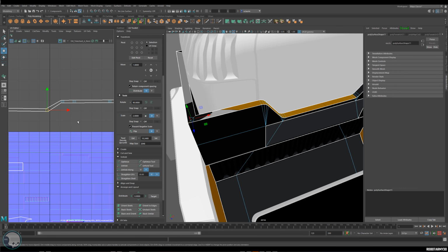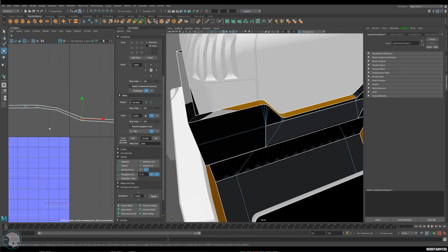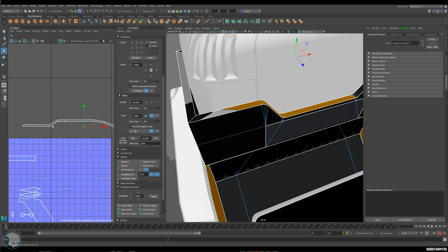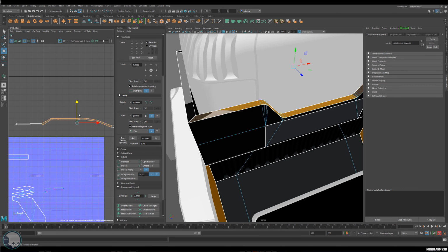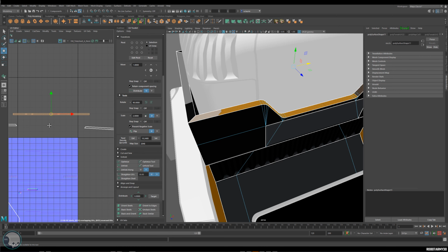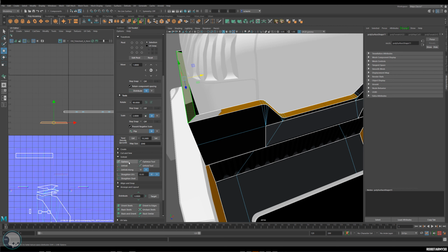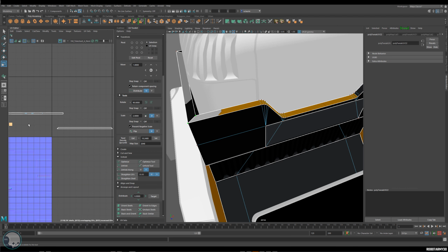Yeah, I think what's best here is to actually cut these open. It doesn't really like these squares, so if we cut them and move that up, optimize and straighten, that should do. And again, straighten, optimize, straighten, optimize, straighten, optimize, straighten, and then I'm going to grab these UVs here and just straighten them as well.